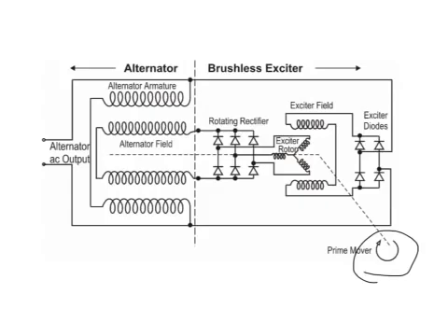In order for this thing to work, at this point we have no load attached at the alternator output over here. There's nothing attached. All we're going to do is look at where current flows once this thing starts turning. Right now, the prime mover is going to bring the rotor part of this machine up to rated speed. There's only one place for current to flow in this machine with no load attached, and that's this way to the brushless exciter. So current starts to flow this way, like so. And remember, this is AC current because we're connected to the same two points.